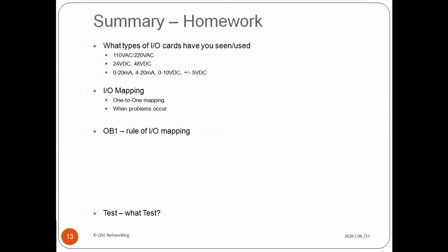On the analog inputs and outputs, as you can see, there's different versions of signal. The key problem you have with the 0 to 10 volts and the 0 to 20 milliamps is when the signal is broken. Let's say the wire is broken and it shows a 0. You don't know if that's the real reading. So the most common, safest analog is to use a 4 to 20.